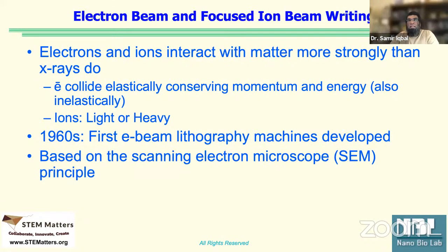Just like photoresist, but in this case we call it e-beam resist. So we coat it, and then when we write with electrons, we control the beam to very precise X, Y directions. The resist undergoes chemical changes, just like photoresist. And when we take it out and dip it in a developer, that pattern is transferred in the resist.